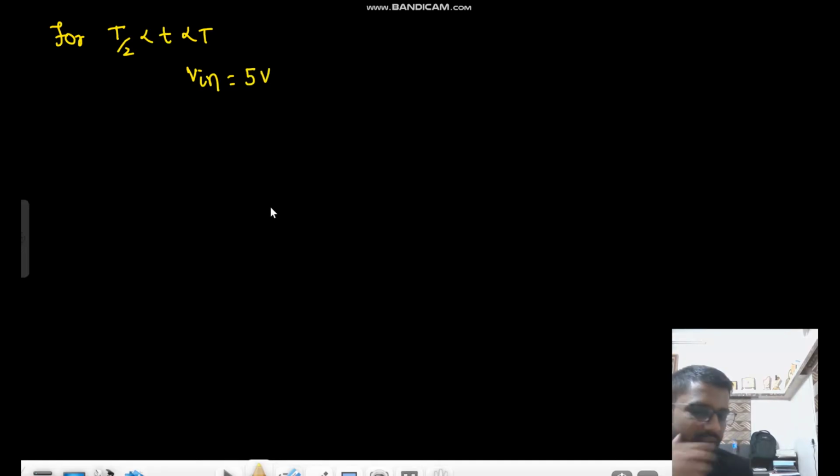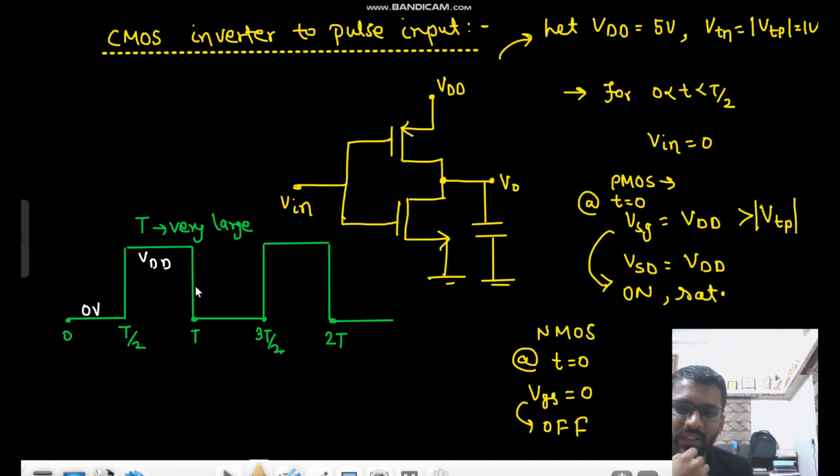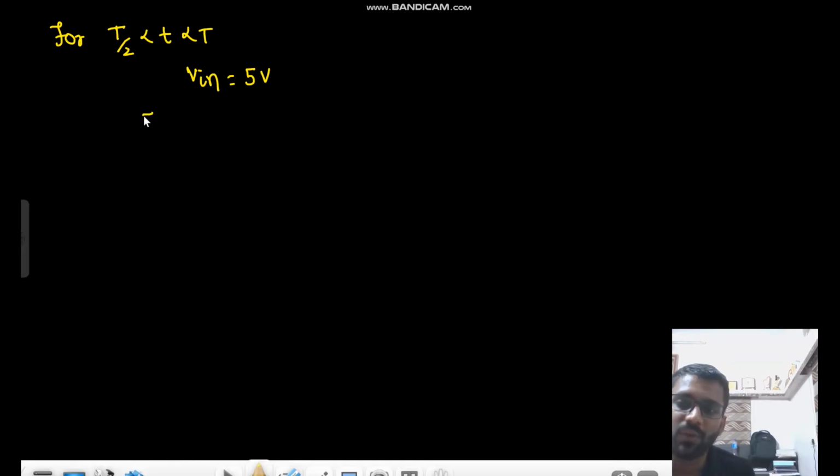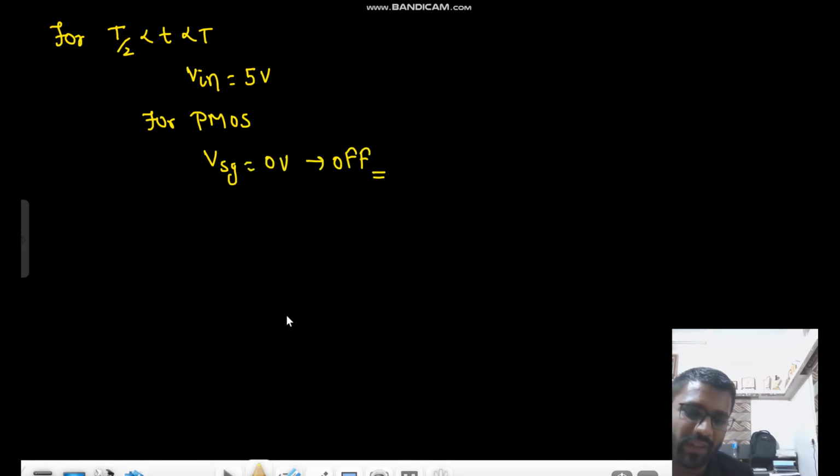Now for T by 2 to time T, your V in is 5 volt, right? For T by 2 to time T, your V in is VDD. That means V in is 5 volt. So now for PMOS, your VSG is 0 volt. That means it is off, right? So PMOS is off. And for NMOS, what is your VGS? That would be 5 volt. What is your V overdrive?